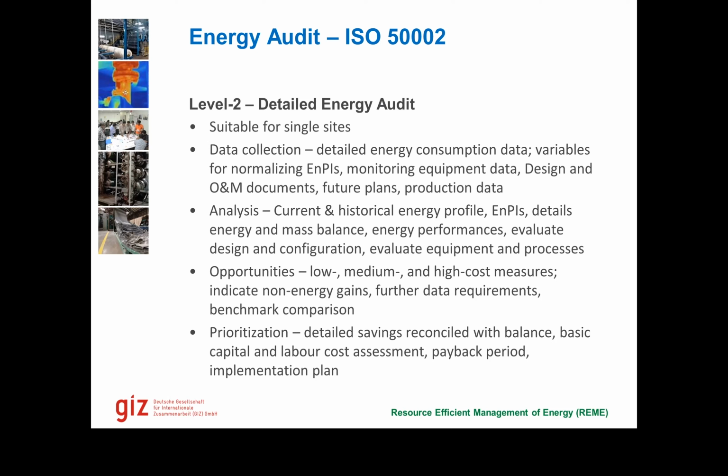And then doing the monitoring using equipment, design and operation and maintenance documents are required at that time. We need to understand what the future plans of the company are. We need to have production data as well. Then the analysis is conducted based on current and historical energy profiles and performance indicators, a detailed energy and mass balance is conducted, and energy performance is evaluated in very, very detail. Design configuration of the machinery, of the equipment, of the facilities is evaluated. And then opportunities can be low cost, medium term, and high cost measures as well.